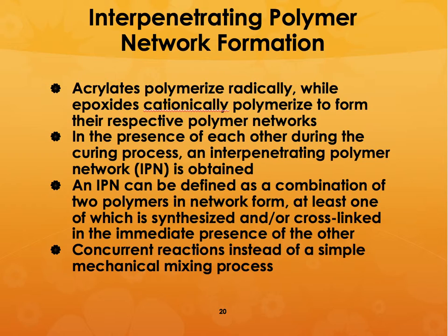So you get an interpenetrating polymer network, or IPN. An IPN can be defined as a combination of two polymers in a network form. One of them is synthesized and the other one is cross-linked in the immediate presence of the other.